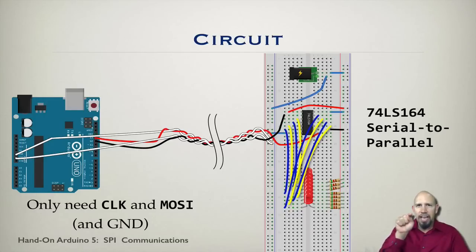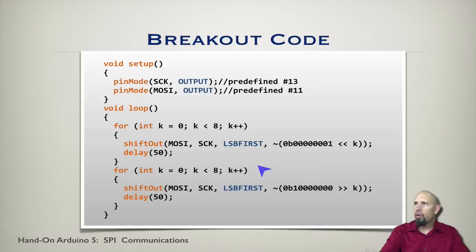So if one of the bits is set, it'll actually go all the way across, and it'll light up every LED as it goes across. But it all happens fairly quickly, so you don't see the lights flashing. In some configurations, people have reported seeing the lights flicker a little bit when a bit goes by, but in many cases, depending on how you set the resistor values, you may or may not get any flashing. So this is the circuit that we're working with and our problem. We're now going to look at the code to see how it works.